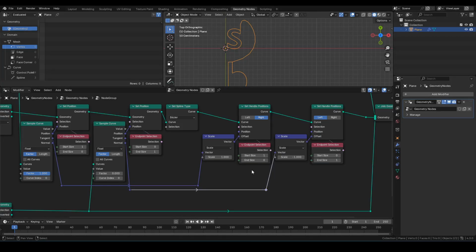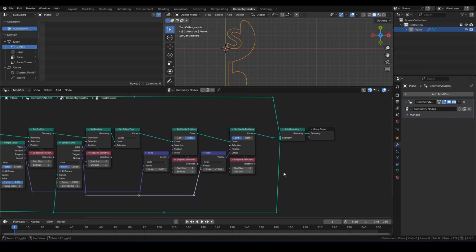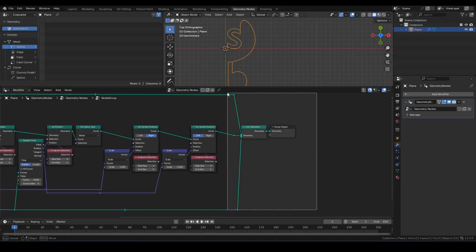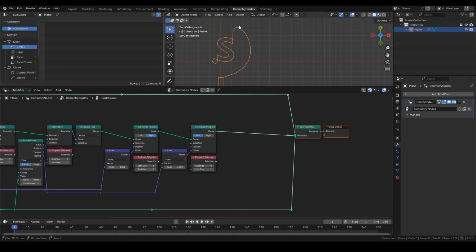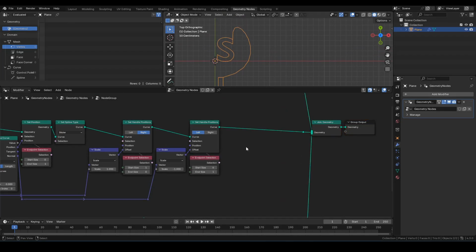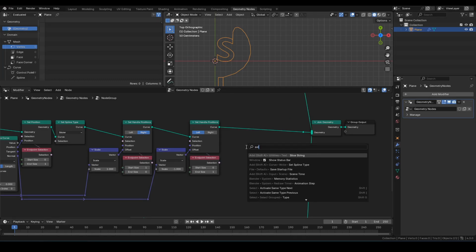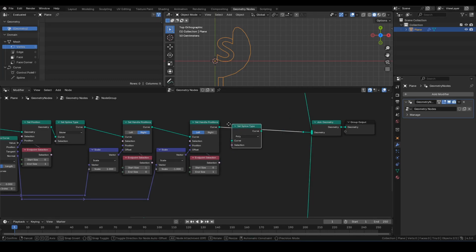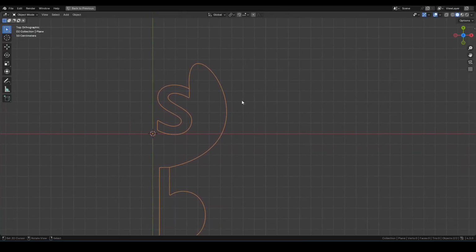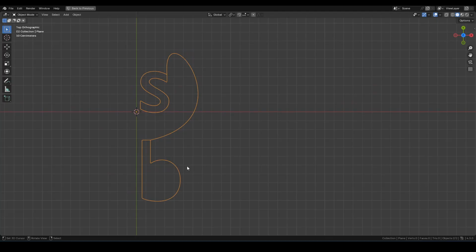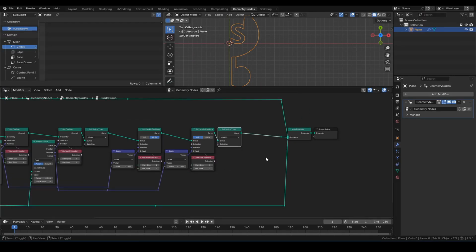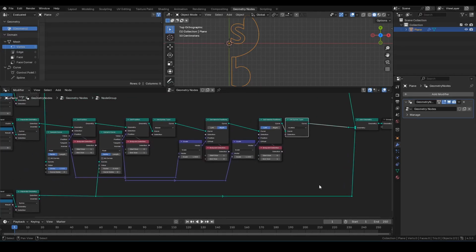Alright. So we got the guide splines connected the way we want to, but it's a little jaggedy. You can see these edge corners, so let's change the spline type again. This time we'll select NURBS. Right, so as you can see, we get this nice smooth curve going from S to B. Okay, right, so we're done with making the guide spline.